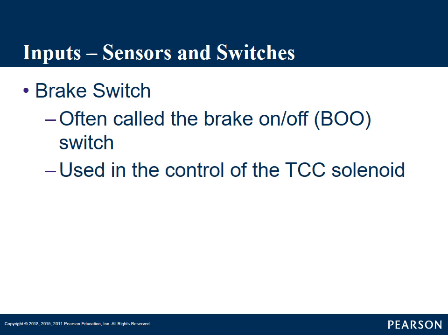Most transmissions with lockup torque converters have to be hydraulically in a higher gear than first gear for it to actually even work. So in many transmissions, even if the lockup was stuck, you could come to a stop and it wouldn't stall the vehicle, because the hydraulic pressure that applies the lockup is taken away by the time you get down to first gear.